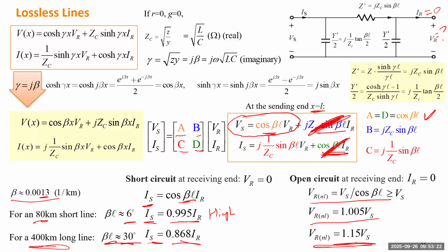So if I have a 500 kV line, 5% times 500 is 25 kV. So you want to operate at 475 to 525 kV, within 5%. But if you go to 15%, that's like a 75 kV difference compared to the nominal value. So when you open the circuit for a long line, that can be a big problem. This can be a really big concern.